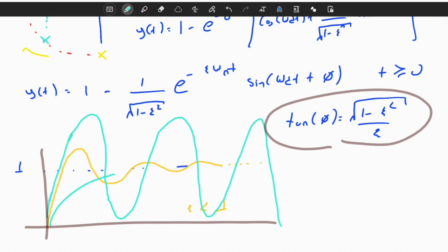The amount of oscillations is decaying. So as t goes to infinity, it reaches the steady state value, which is nice. But in between, I observe some sort of oscillations. I really don't want these oscillations, or I want them to be as small as possible. This part is overshoot. I will talk about it in the next lecture. It's called overshoot. We will try to minimize that, and adjust other performance metrics.